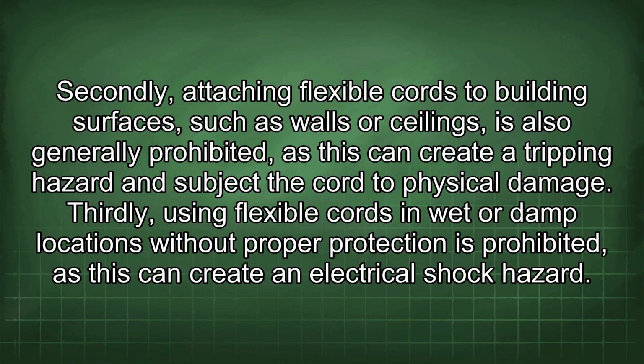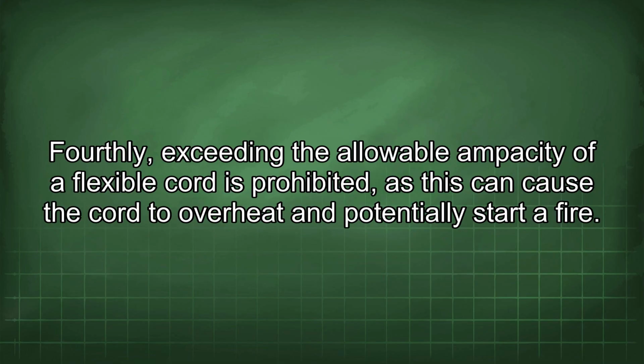Thirdly, using flexible cords in wet or damp locations without proper protection is prohibited, as this can create an electrical shock hazard. Fourthly, exceeding the allowable ampacity of a flexible cord is prohibited, as this can cause the cord to overheat and potentially start a fire.